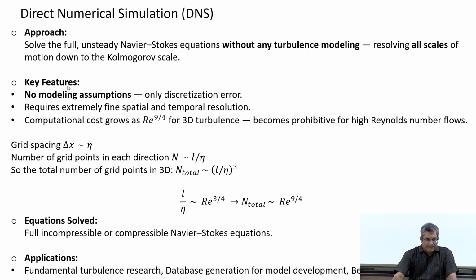I have already discussed the advantages and limitations of the direct numerical simulation approach, where you don't rely on any models, rather you try to resolve the turbulence at all scales. So you resolve the turbulence energy spectrum fully, but the main issue in this case is the computational time.